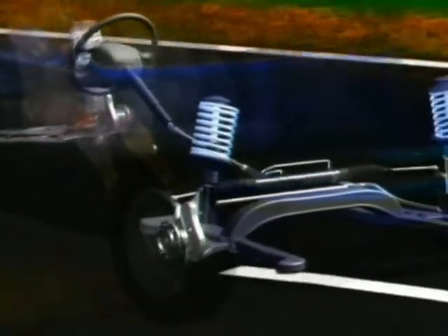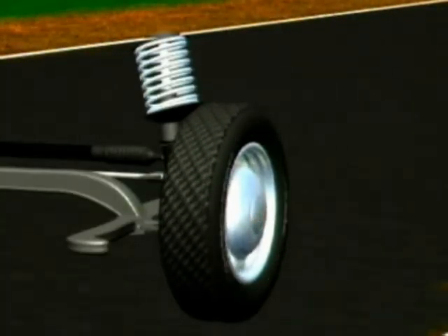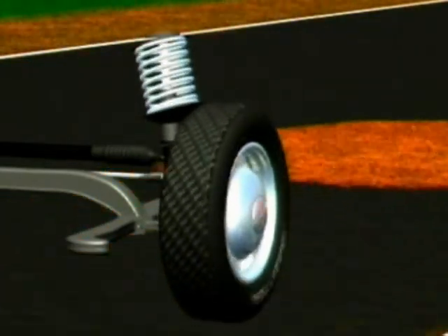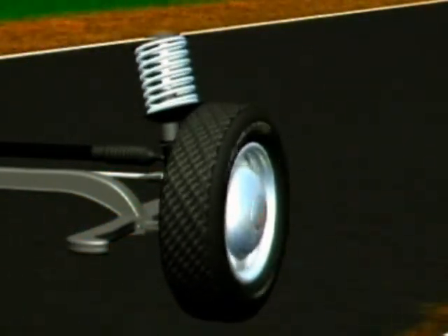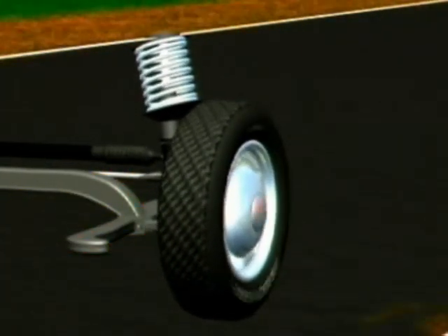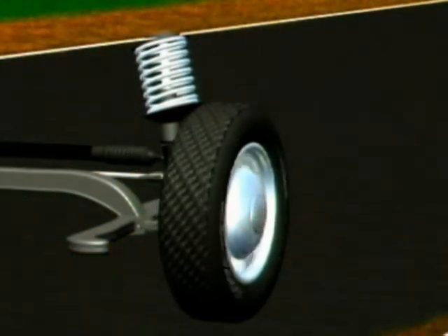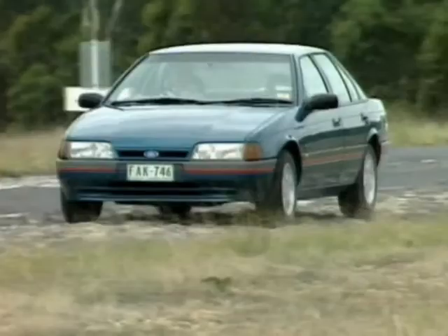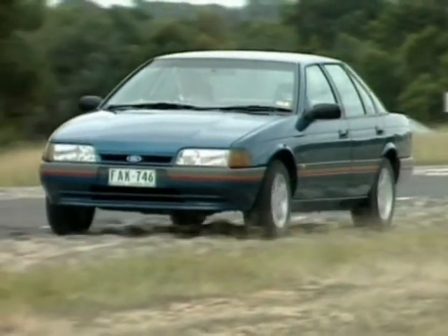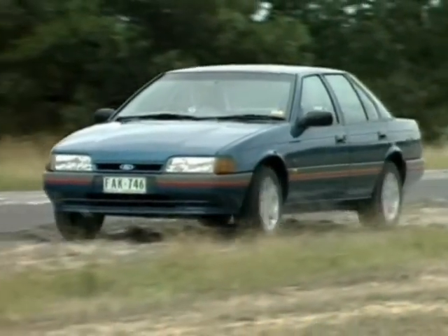Vehicle ride and handling can be improved by keeping unsprung mass as low as possible. When large and heavy wheel assemblies encounter a bump or pothole, they experience a larger reaction force, sometimes large enough to make the tire lose contact with the road surface. Wheel and brake units that are small and light follow road contours without a large effect on the rest of the vehicle.